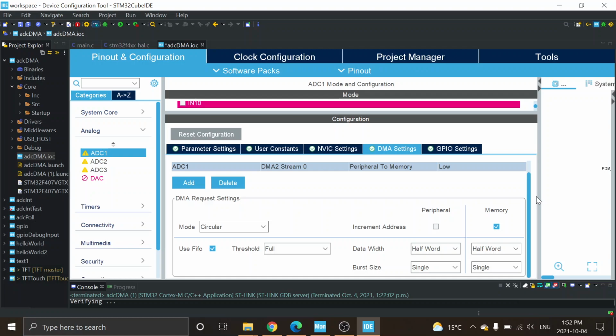The other thing here, which can get you messed up, is that by default it knows the data coming back from the ADC is 16-bit. It's a 32-bit register, but the upper 16 bits are reserved, so a 16-bit value is coming back, and all you need is a half word. The libraries that you use with HAL, anytime we've highlighted them, say it's a uint32_t, a 32-bit value coming back.